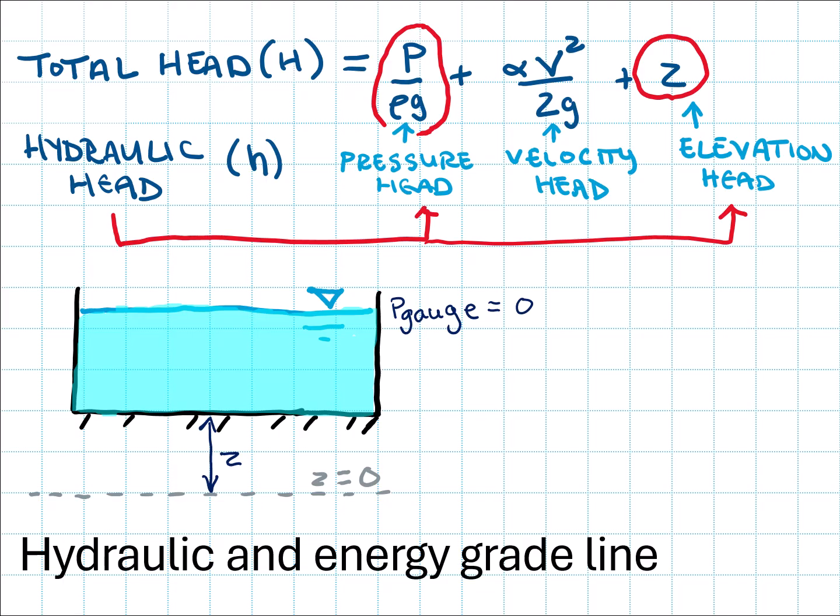And so down here at a point at the bottom of the channel, at this point I know that the pressure is going to be equal to the density of the fluid, the gravitational constant, and the height of the fluid column above that point, right? So that height h would be from the free surface down to the channel bottom. And so you notice that this is the depth of flow in the channel. So let's look at something neat here.